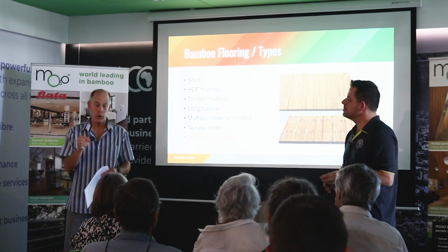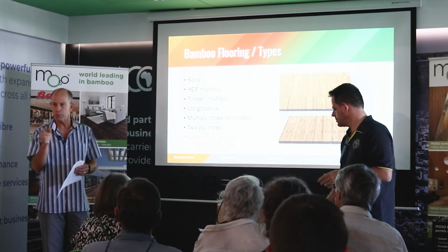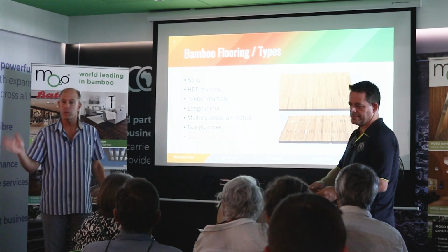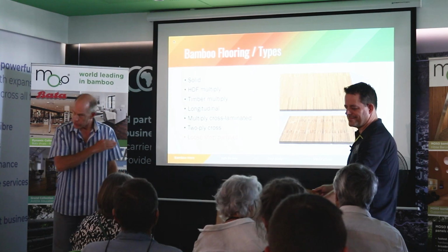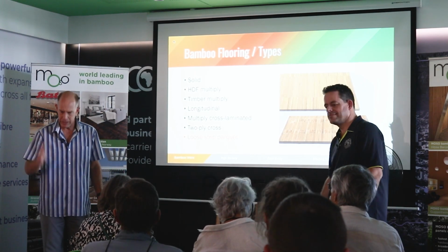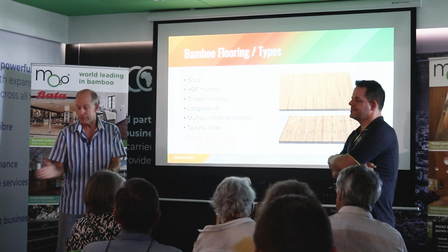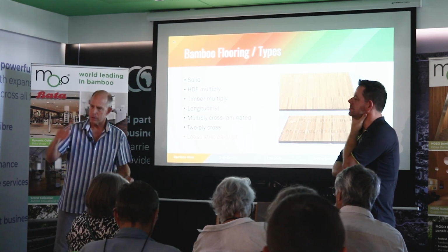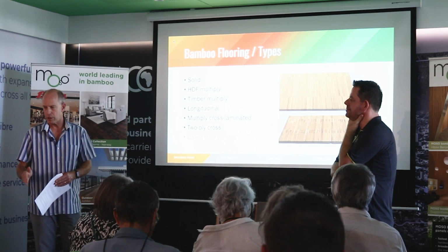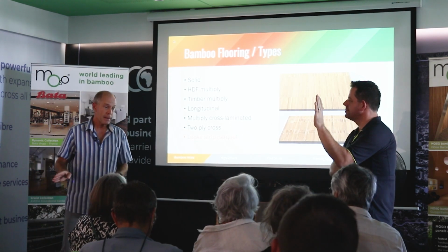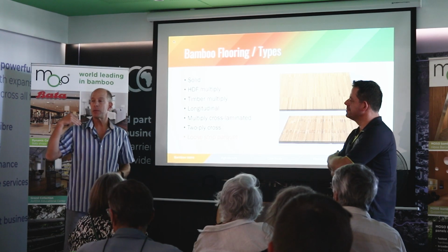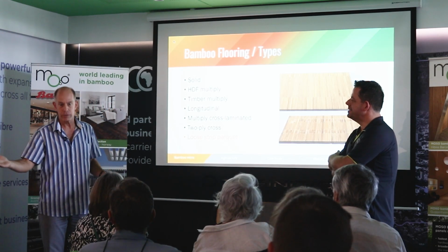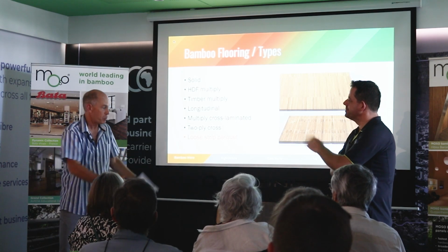They are microscopic, you can't see them, spaces, gaps between each board. So again, you can have hundreds or even thousands of square meters of this installed with no joints. You don't need air expansion gaps. You can put it right up against other flooring types like tiles. You can put it up against pillars, up against walls with no gaps. It's a very versatile floor, glue down only. It's relatively cheap to produce, and we sell it at a reasonable price because it's just strips of untreated timber.